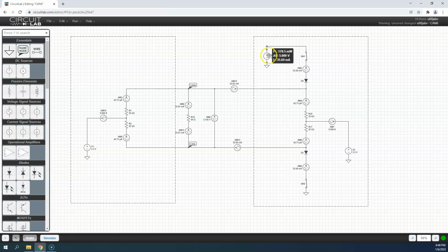What's happening is this 5-volt supply inside this device, whatever this is, engine controller, transmission controller, who knows, there's a FET that's switched on here. We can see there's 35.69 milliamps. We go through this diode. We come down to this point, and be careful here, this is 42.73 microamps. So this is about 1,000th of what this is. It's a very small piece of it.